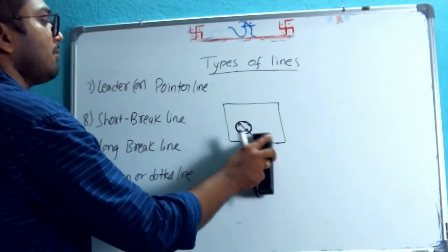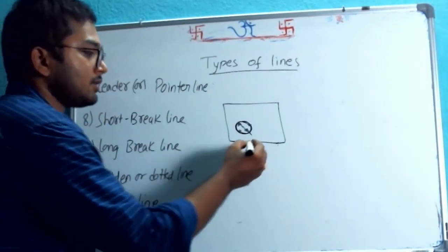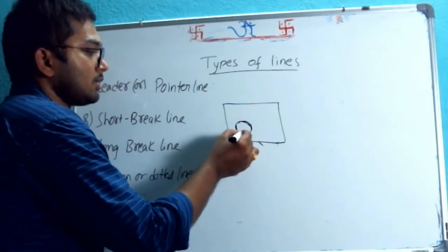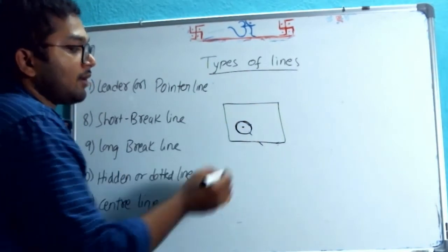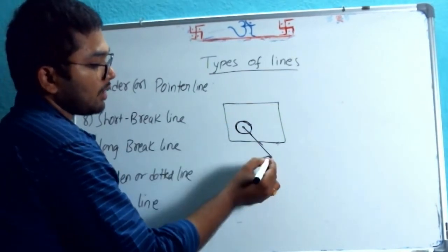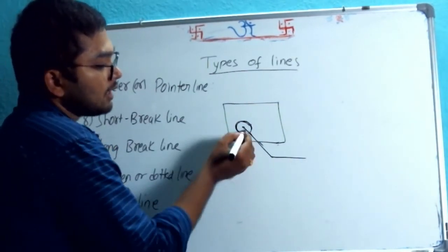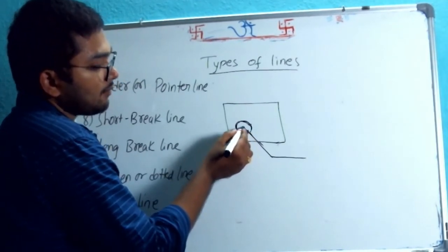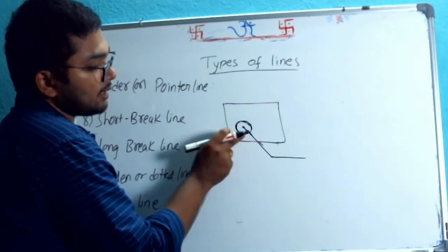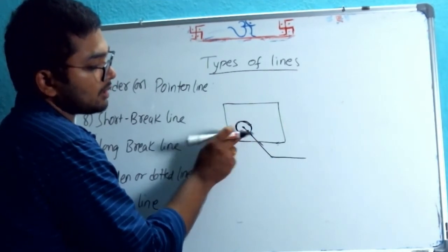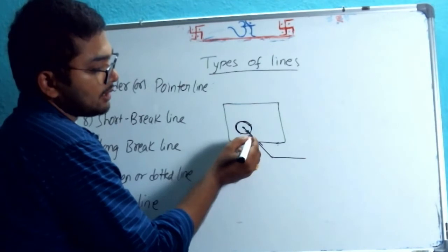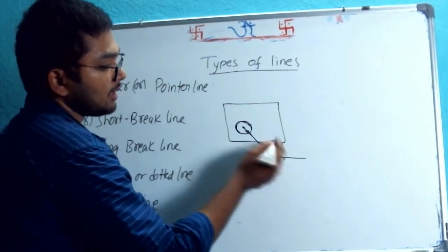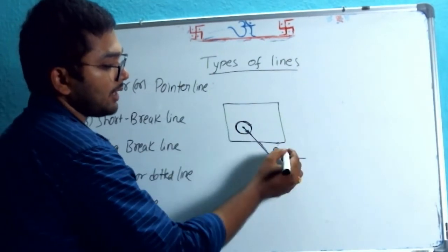Radius wise also we can mention it. Same hole. From the center, draw a straight line. There, only one edge, like a ray. From the center, you draw a ray, with an arrowhead on one side of it. They extend it like this. So here we can draw R. Say it is 20 mm diameter, so radius will be 10 mm.